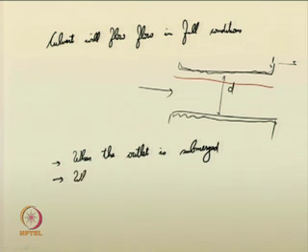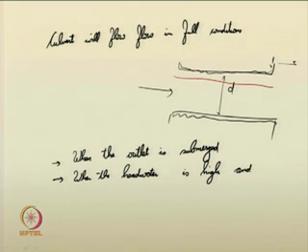Or when the head water, or the inlet water, is high and the barrel is long, you may have full water condition. So, if the water at the inlet is much higher, then it may flow fully. These conditions suggest that the culverts may flow in a full situation.